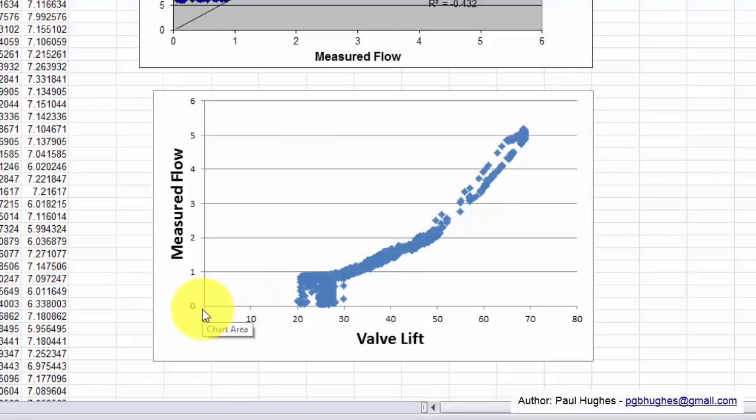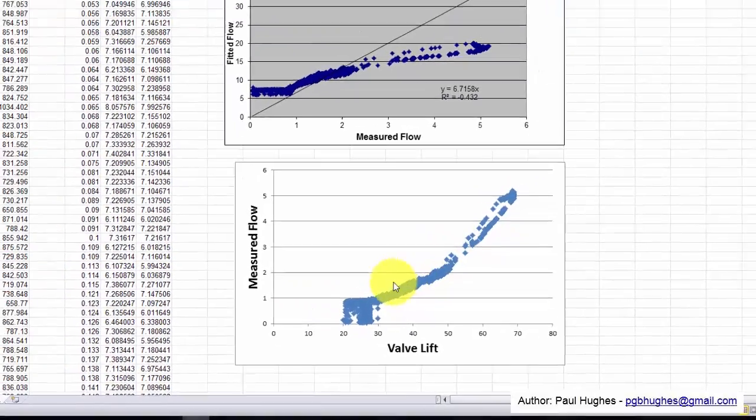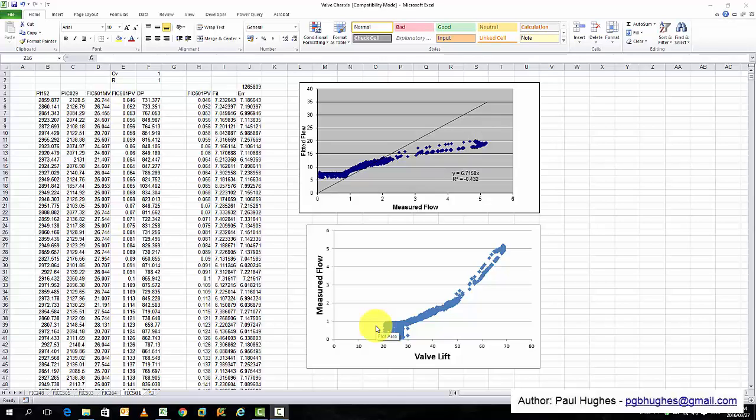In regions which I've cut off below 20%, it becomes unreliable. Normally, you have two options that you can configure in systems. You can configure to freeze at a value which will be above 0, or you'll have the noise in the signal. So now, based on what we've shown already, the idea is to see if we can fit a curve through here so we can get a good idea of how to estimate the flow in this region over here.